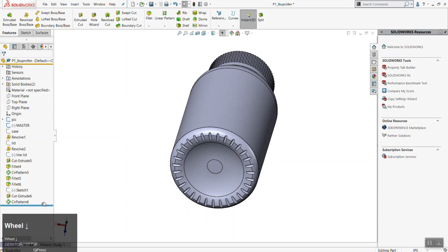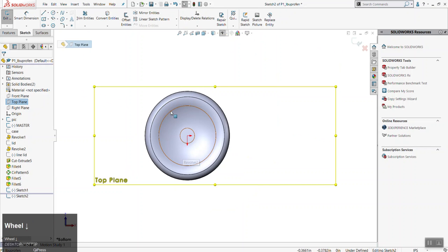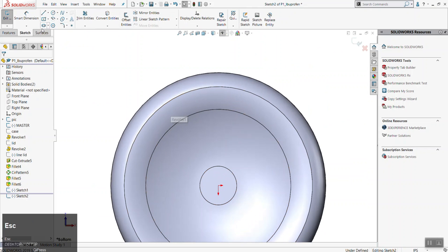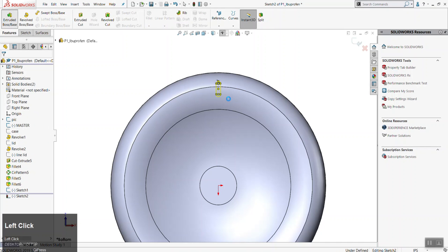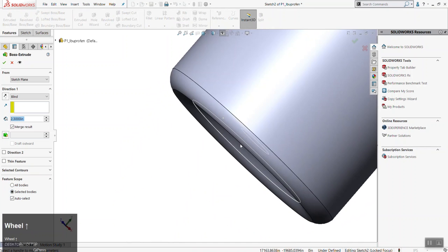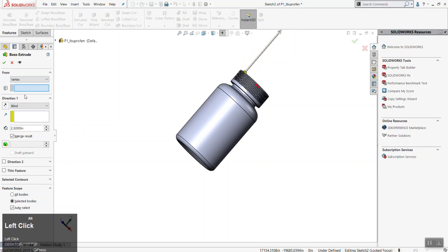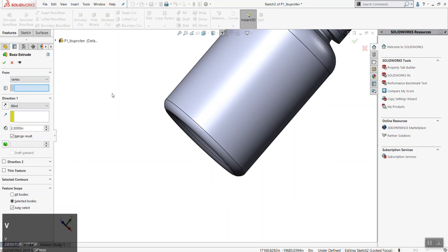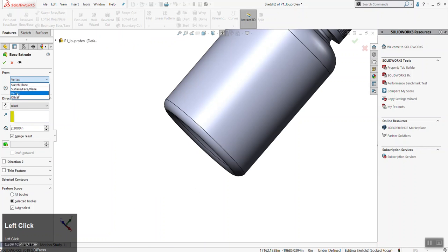Yeah, a bump instead of a cutout. Let's look at that real quick. It's basically the same thing. You could do an extrusion. Yeah, you could do a slot shape here. Extrude. This is where, I think Max was asking me this. Actually, here I might do, pick a vertex. I'm just going to offset this.